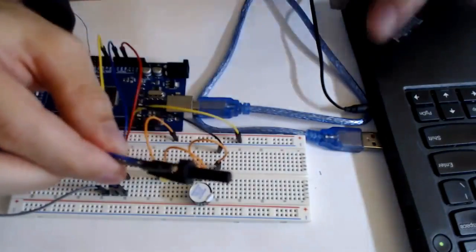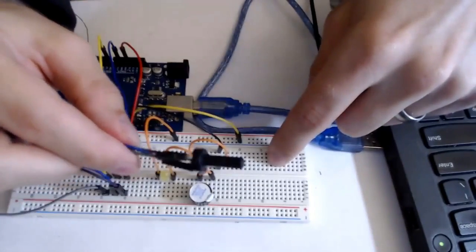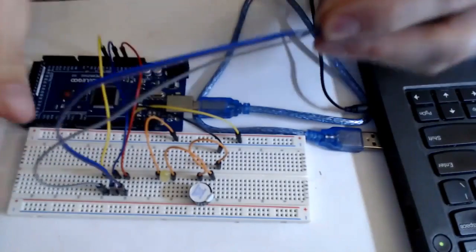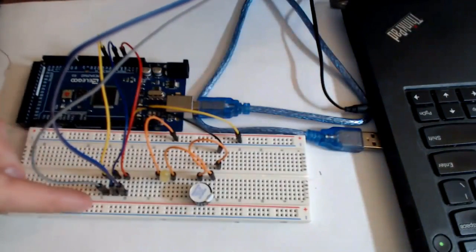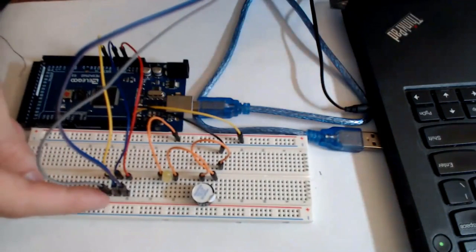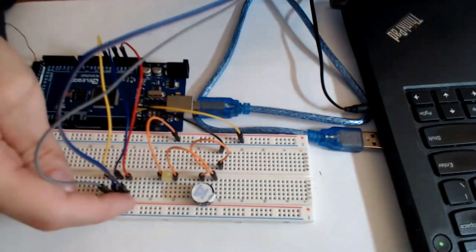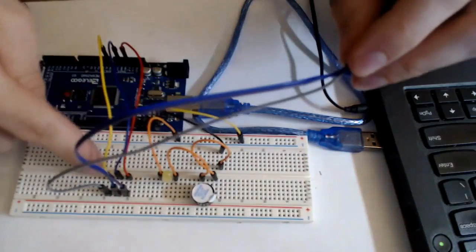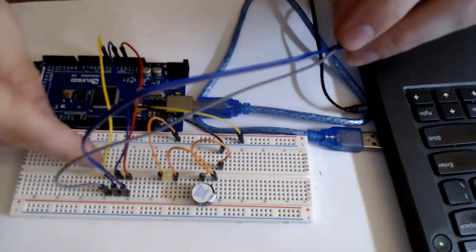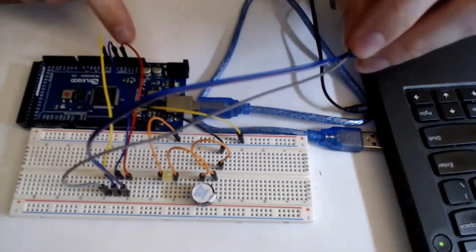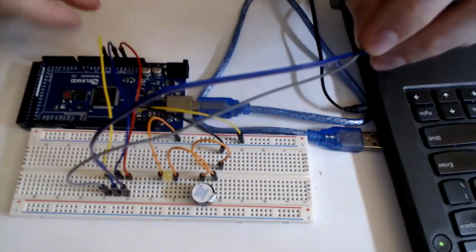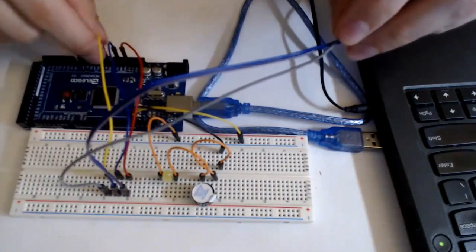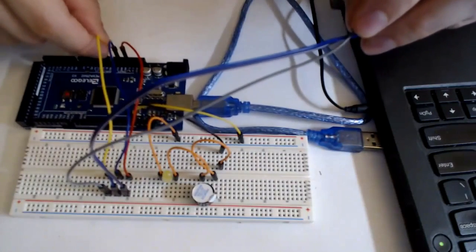Those little legs don't fit very well into the holes of the breadboard, so it's kind of necessary to attach some wires to it. And those wires are going to be now nicely lined up like they were in the PowerPoint figure right here, from 40 to 42 to 44. And then those columns are attached all the way back here to the analog side of the Arduino. In the ground, the plus 5 volts, and the yellow one here is the analog input 0.